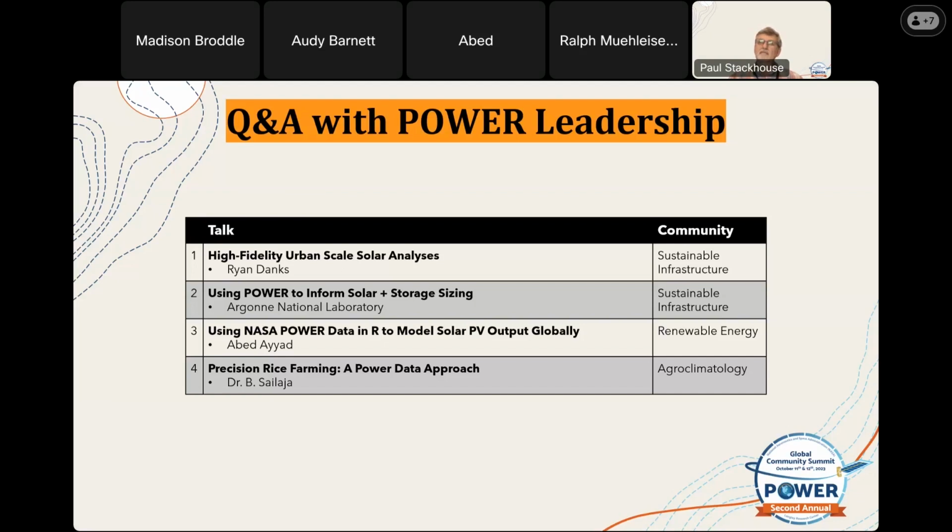Actually, Abed, this is Ralph. Yep, I can comment on it because I just analyzed solar at least all over the United States at 450 locations, and the answer is the correlations that people had are pretty poor. So the good thing is that if you're looking at total production as opposed to power, and you're looking at how many kilowatt hours, it isn't as big a deal. So whether you're at low latitudes or high latitudes, if you're doing things at 5 or 10 degrees below latitude, you're going to have a pretty good output, but it's pretty forgiving.